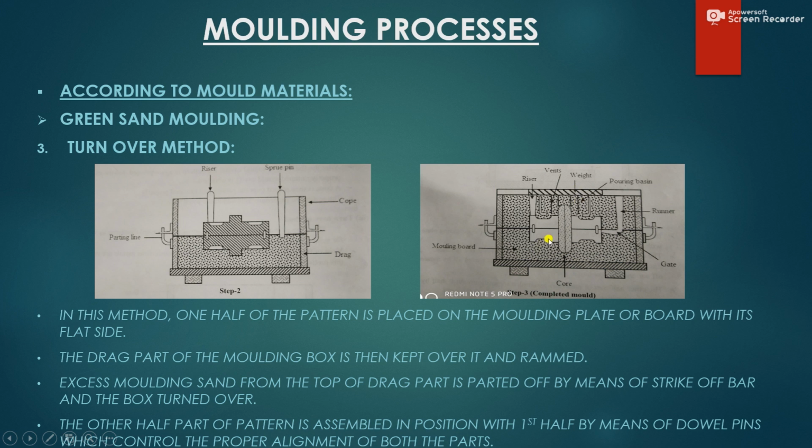If you need to put a core inside it, if the casting that you're supposed to prepare has a core inside it, has a hollow portion inside it, then in the cavity that is given here, you can put a core as well. The basically previously prepared core you place here, so molten metal will not go in those portions, and that portion will remain hollow.